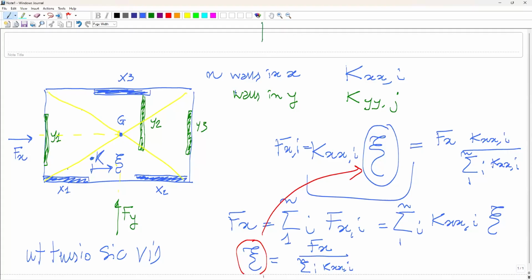But before you make the analysis and design your walls, you don't know how the stiffness will drop because you have not designed it yet. So you cannot calculate how much your stiffness will drop because of cracking. So the codes tell us that in the analysis, you can consider the effect of cracking, and you assume this stiffness equal to 50% of the gross solid stiffness. So you still keep the linear elastic assumption, but because of cracking, you reduce the stiffness.